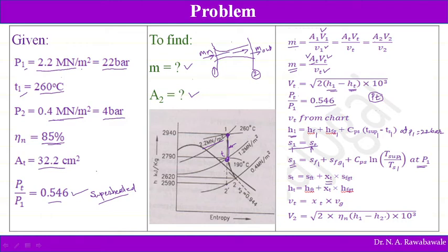In this diagram it is shown that steam is superheated, which is above this curve. That means if this point T is above this point, then we say steam is superheated. If this point T is inside this curve, then we will say steam is wet. Presently he is saying that steam is superheated. This is the assumption in this diagram, and we will see whether steam is superheated or wet. Then from that we can find out quality of steam, and then enthalpy of steam HT at throat. By substituting HT and H1 in the above equation, we will get velocity of steam at throat.